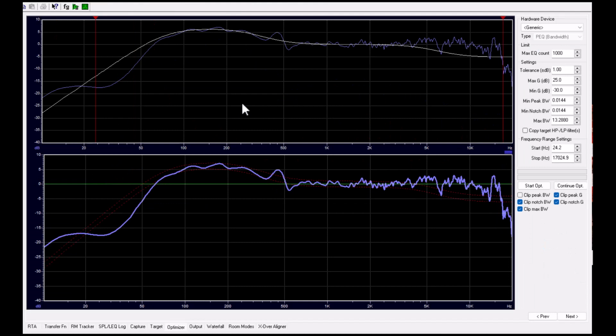In many cases, your hardware doesn't allow for thousands of parametric filters. Usually there are only 12 in your DSP in the amplifier, for example, and you want to use these filters as efficiently as possible. So one way is to steer those filters in an efficient way.